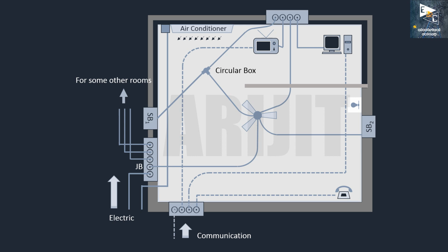In the white enclosed area, you can see in the picture where the electrical conduits have been landed. You can assume it as a top view of a particular room having a couple of electrical points. To connect all the points, 20 mm conduits usually are used for this purpose. There are grayish boundaries surrounding the area. Basically these are the brick walls underneath the beams, and you need to make holes as per dropping the conduits.